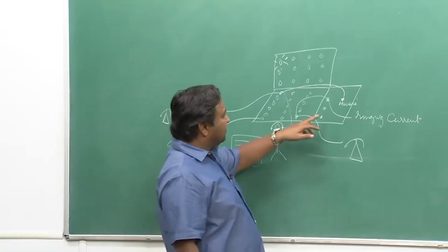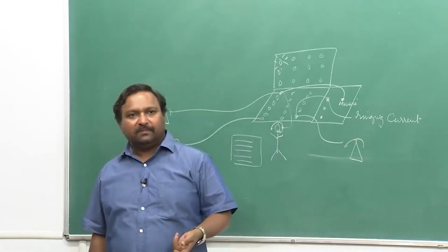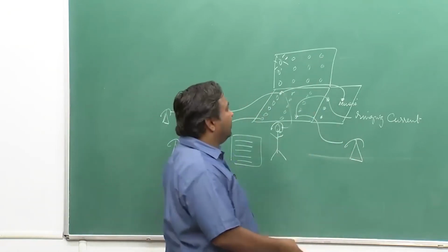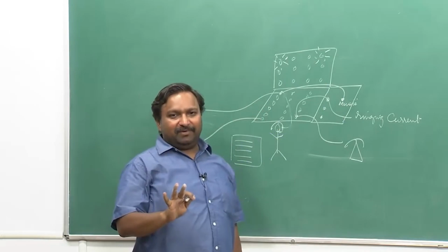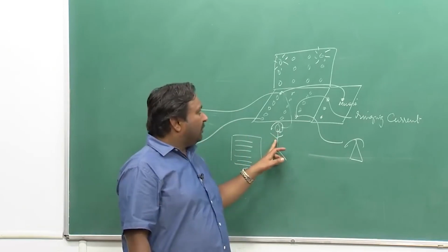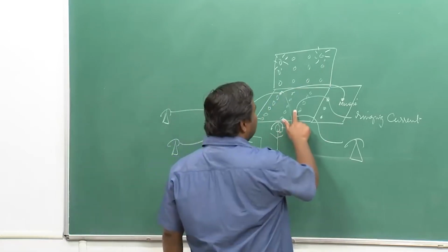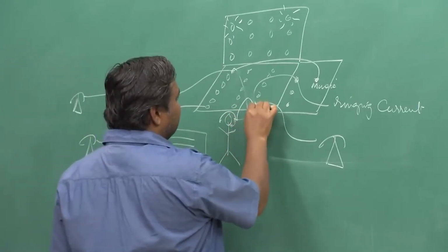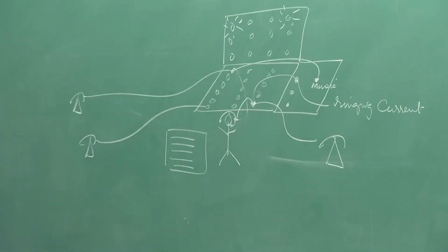Okay. So, once that is done, this ringing will happen, and the user will now pick up the handset. Once the user picks up the handset, the light will glow here correspondingly. The phone will still keep on ringing; remember, just removing the handset will not stop it. The operator will see the person has acknowledged, he has lifted the handset, and she will remove this jumper. So, ringing current is no more being applied, and she can connect her headset here and talk to the person, saying so and so person wants to make a phone call to you.